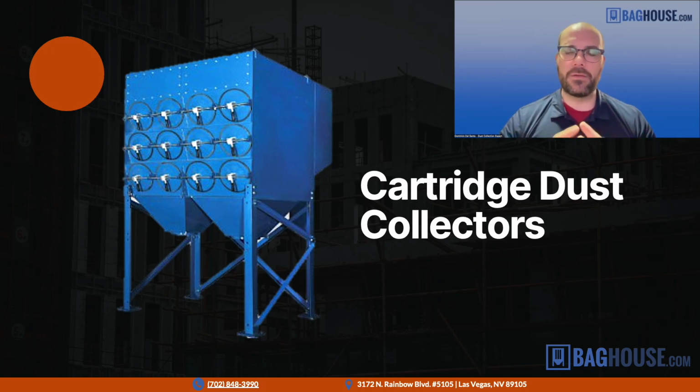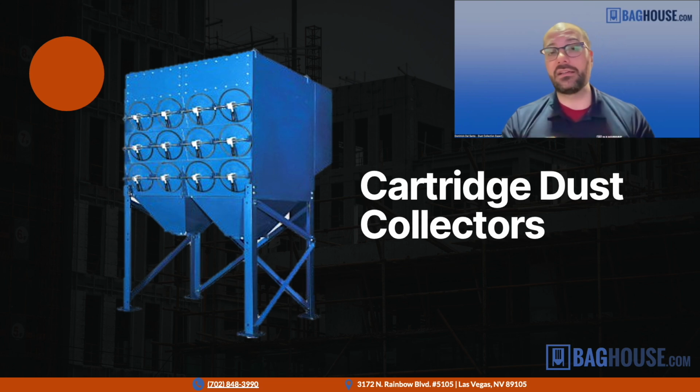Now, there are some differing opinions. A few manufacturers recommend them for cement and mining applications. Most in the industry, however, decide not to use them. If you are going to use them in a mining or cement application, we do recommend you use the other style where the cartridges hang vertically, as opposed to this style you see here where they're horizontal, because this can have problems where the dust builds up on top of the filter and it can't be cleaned off when there's a lot of dust coming in.